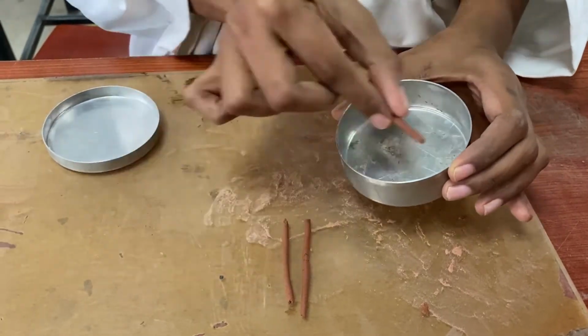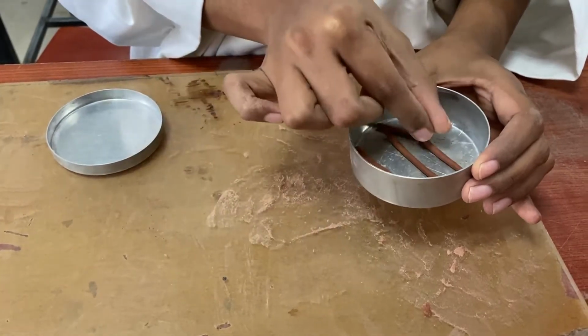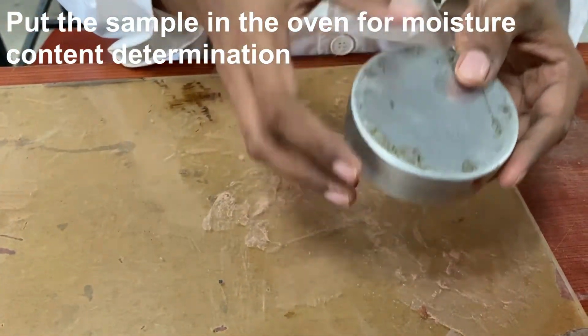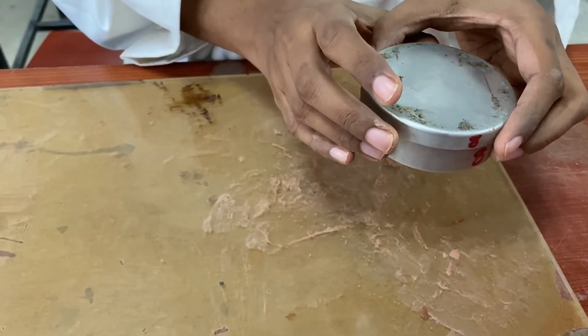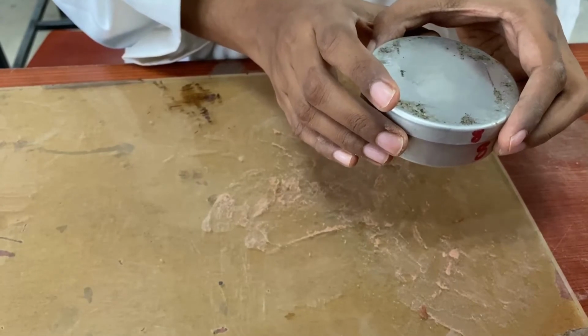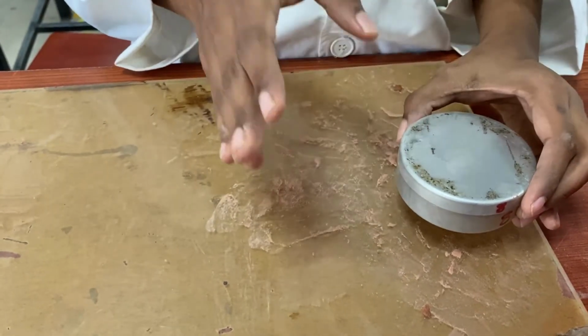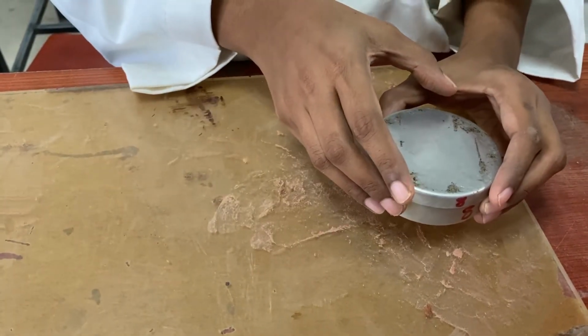You may keep all these 3 samples in one and record the weight. After 24 hours, you may take the weight again and see the moisture content. Likewise, we will have to do this for another 2 trials for the plastic limit determination.